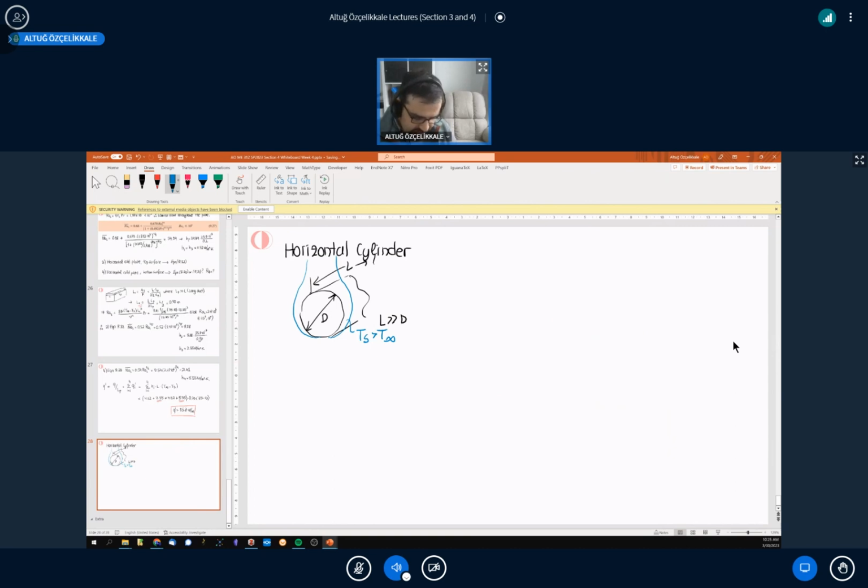So there's clearly going to be convection heat transfer that depends on formation of this boundary layer and then detachment of the boundary layer. The situation is kind of similar to what we have considered in cylinder in cross flow. Remember the variation of Nusselt number across the surface, starting from the forward stagnation point. We would have this Nusselt number depending on the angle, but it would also depend on laminar or turbulent conditions, whether and where the flow detachment would occur over the surface and so on. It's complicated. However, the heat transfer correlations are not that complicated. So let me show you one.